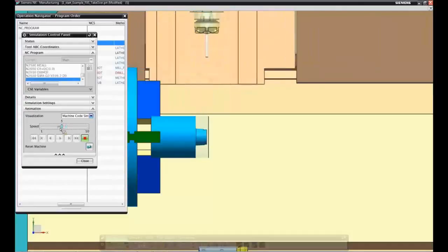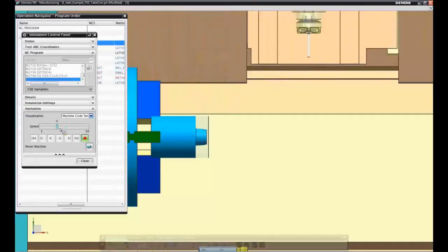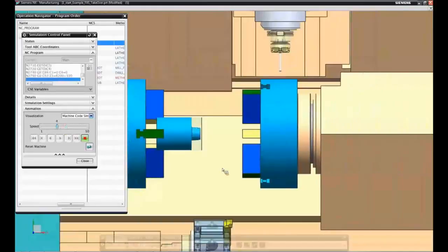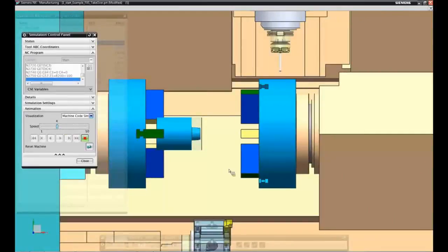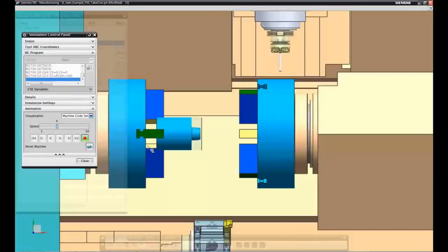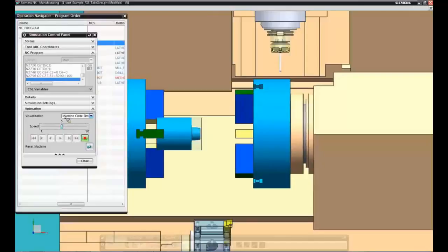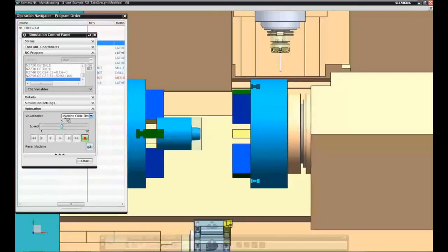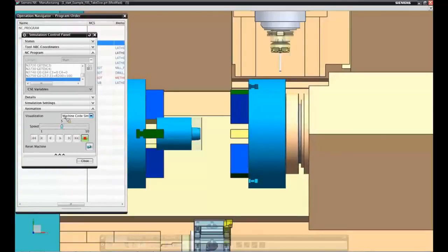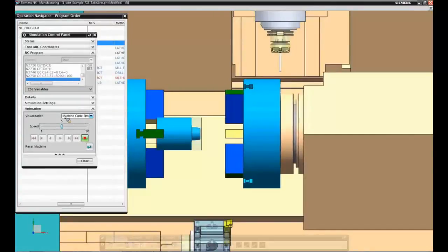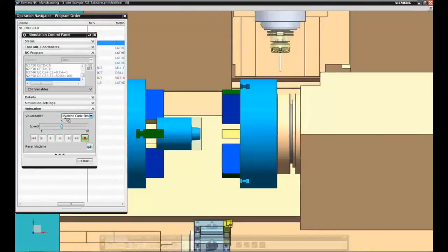Now the sub-spindle will move and come, and now it goes to a feed rate, and now it checks for collisions at this point, but you will see that it's too far away, and it will not find a collision within this 100 millimeter range, which I typed in the dialog. And after a certain time, it will give me a controller error message here in the dialog.